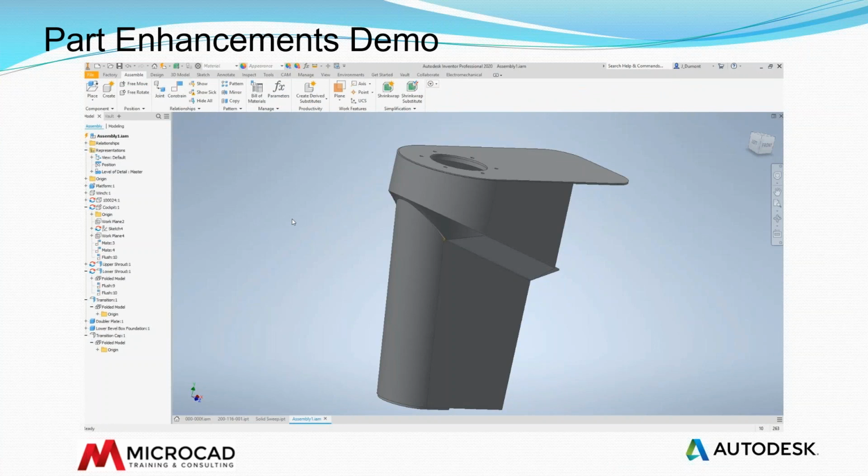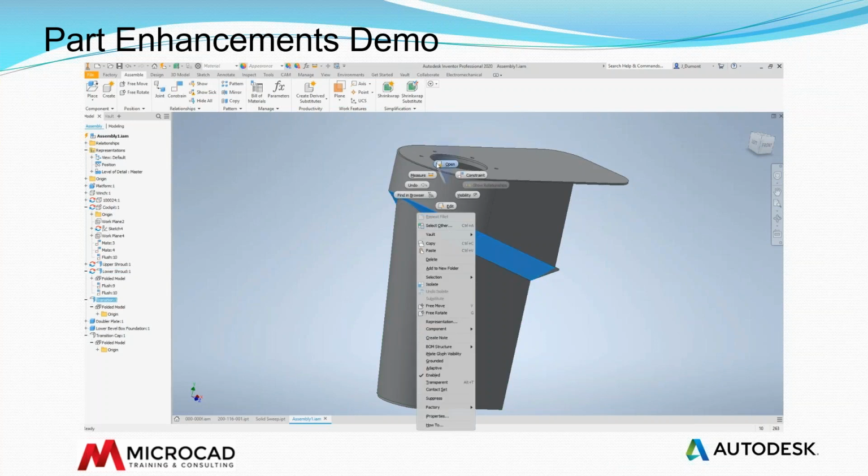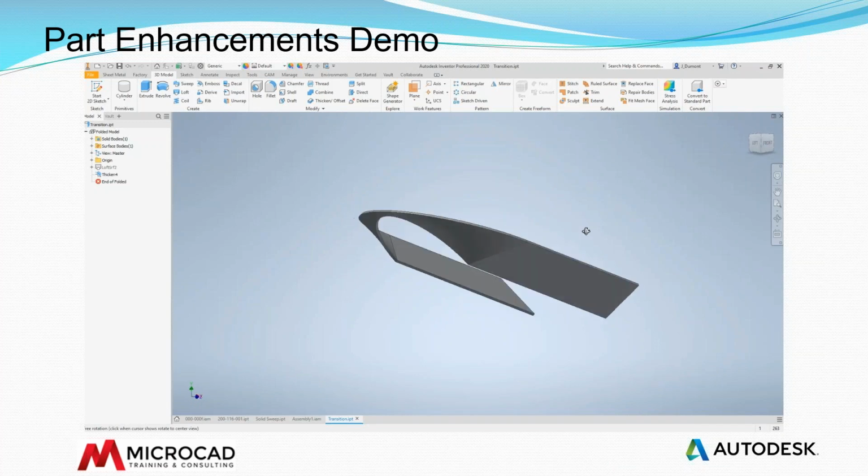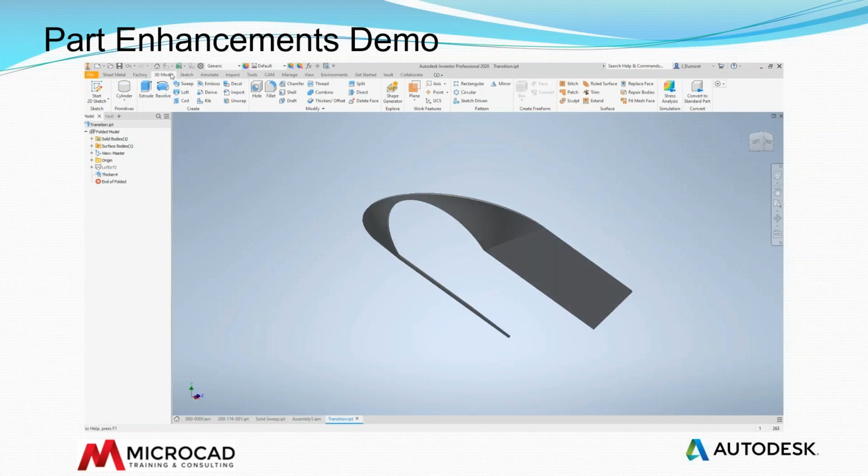The last thing in the part environment we'll look at is the unwrap feature. I'm going to take this solid body, that's the sheet metal component, and I'm going to look at it. Now, this was created with a walk command, so creating a flat pattern from this is virtually impossible with Inventor 2019 or earlier. So what I'm going to do is use the new unwrap command, and I'm going to select my faces.